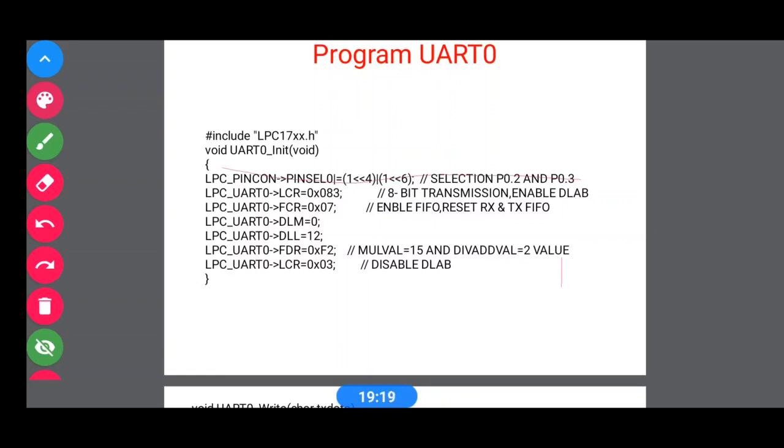Bits 6 and 7 of the pin select 0 register are associated with pin 0.3, and this is also the first function, so bits 6 and 7 we are writing the value 0, 1.